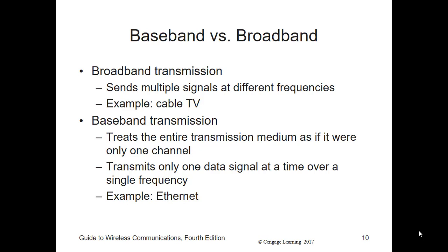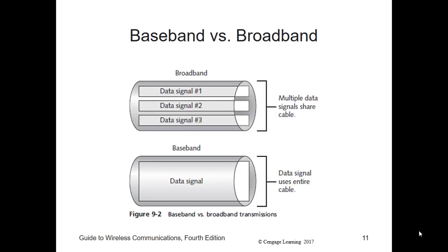Purely digital signals can only be transmitted over a wire as baseband because mixing multiple voltage changes on a cable would create different bit patterns and basically just corrupt the data, given that there's no way to separate one signal from the other. However, if you modulate multiple digital paths over different carrier frequencies, they can be transmitted over any analog medium. The receiver can then separate each frequency using filters and then decode each of those digital signals.